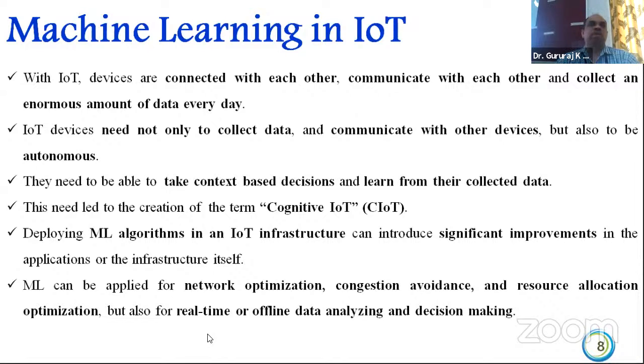Whenever I want to know how many people visited a particular mall on a particular day, there's no need for anyone to keep a person standing there counting nowadays. You can have an infrared sensor over there. It blocks the entrance, and once a person enters, it cuts that particular infrared ray and the counter is incremented. You have two different ways, entry and exit, and as and when a person enters, the counter increases. At the end of the day, you can just check the counter value, and you know how many people entered. And if there are repeated entries, there is again a flaw there, which we need to take care of in such scenarios.